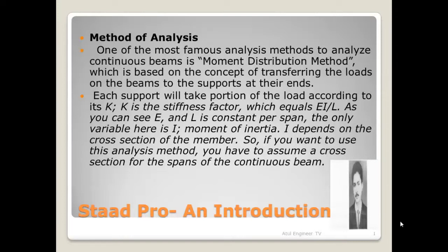Now let us have a quick look at the classical methods of hand calculation. Method of analysis. One of the most famous analysis methods to analyze continuous beams is the moment distribution method, which is based on the concept of transferring the loads on the beams to the supports at their ends. Each support will take a portion of the load according to its K.